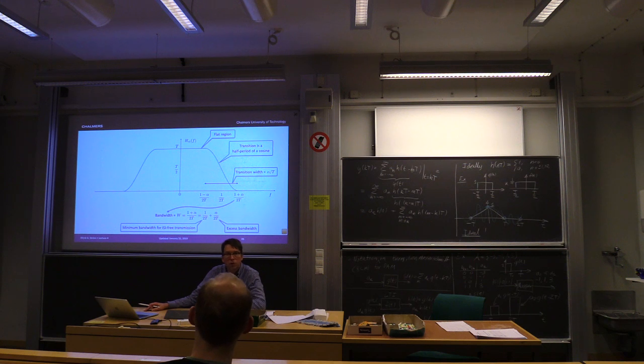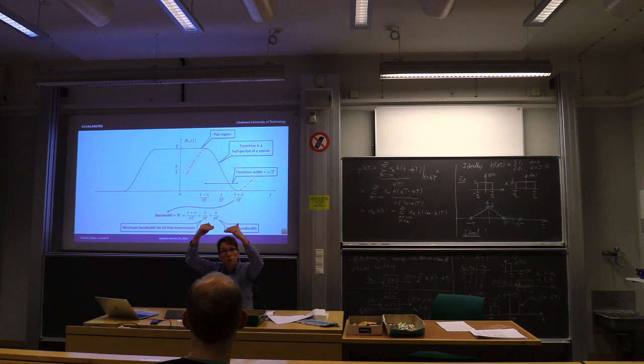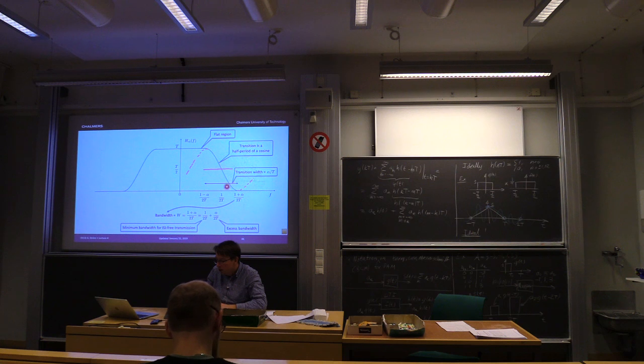It's called a raised cosine because if you plot the spectrum, it's a flat line, and then there is half a cosine that goes like this. So if I would continue to plot the cosine, it would go something like this. Okay, so it's a cosine which is raised up. That's why it's called the raised cosine. You know, it's symmetric around 1/2 here. So it has a flat region and then a cosine shape which smoothly takes this from 1 down to 0 here, or from T down to 0.